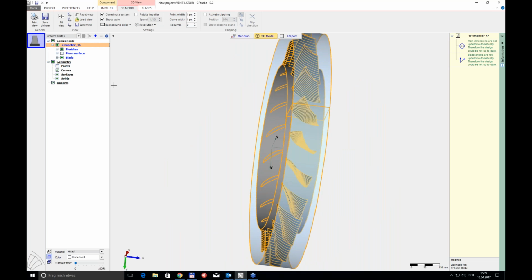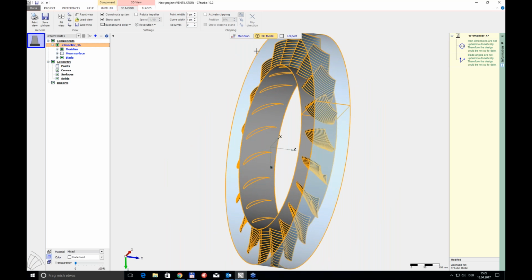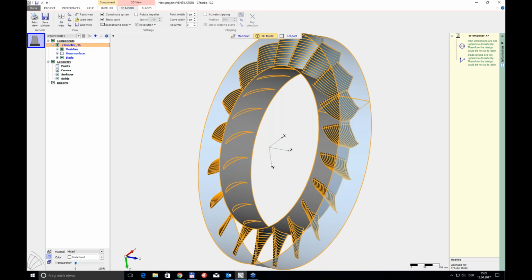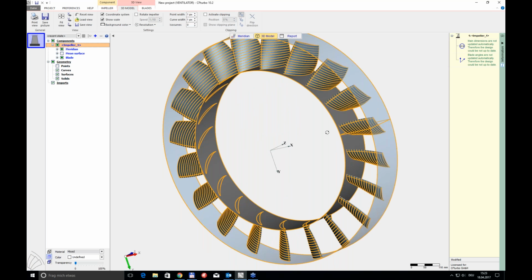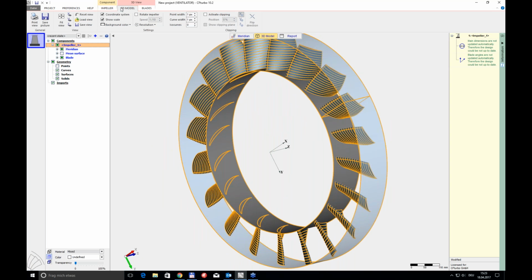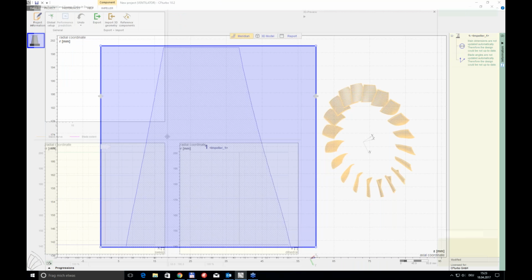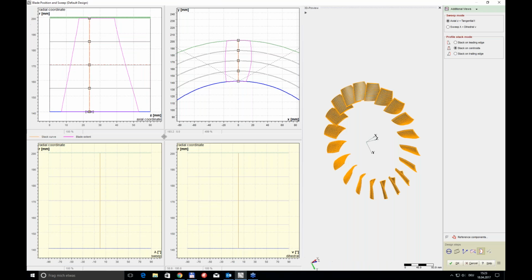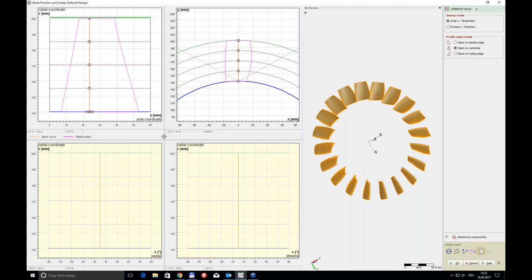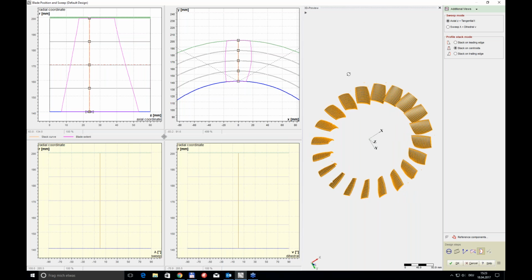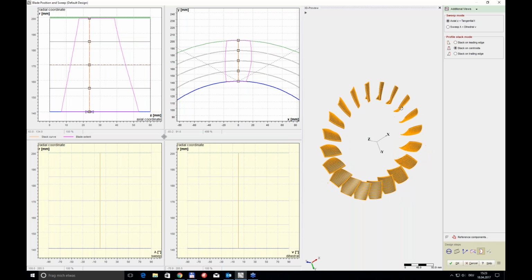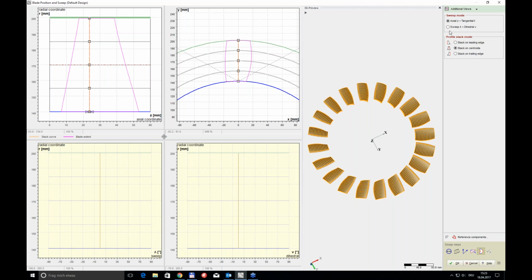Of course, when it comes to the design of actual fans, acoustic performance, or the acoustic behavior when running the fan, is very important, and there is a design step implemented which can be used to improve the acoustic performance, and that's called the blade sweep. And to this end, in two different modes, one can try to sweep the blades in order to get an acoustic benefit.